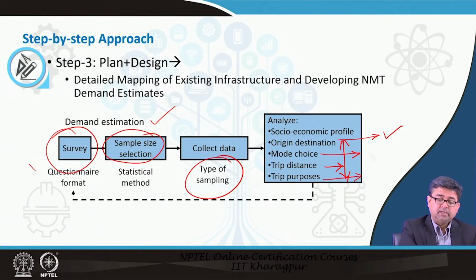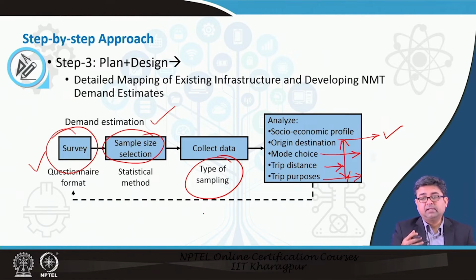So, a questionnaire survey usually is used on a sample population of your city. Remember that there are different scales of non-motorized transportation projects. If the scale of the project is the city, then you have to develop a sample for the entire city. If the scale of the project is just a street, then all you have to find out is how many people live alongside that street, and you have to sample only a few people along that street. Okay.